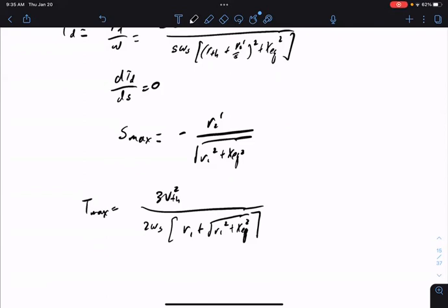Right, so yeah, in class, one way to think about it is the torque on the rotor side: the rotor is part of the torque, so you're maximizing the rotor side. Then what torque is left over is between the rotor and the air gap. That's one way to think of it. But actually, the equivalent reactance shows up. So X2 shows up as part of XEQ. R2 never shows up. Right?